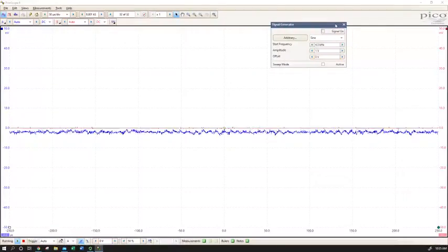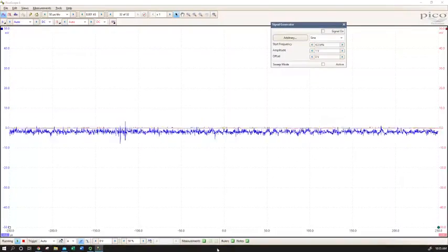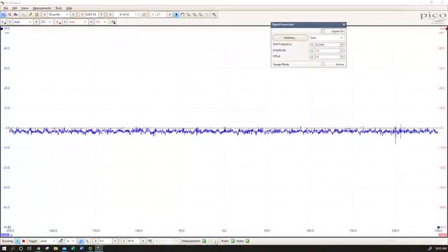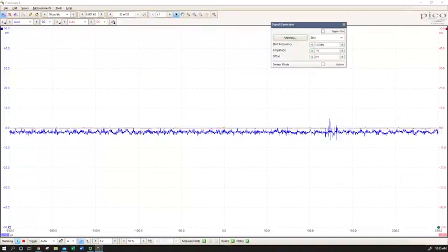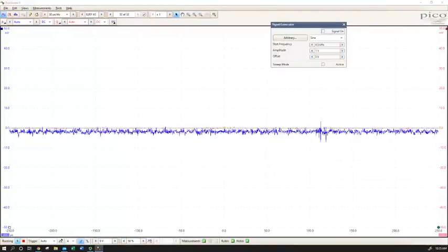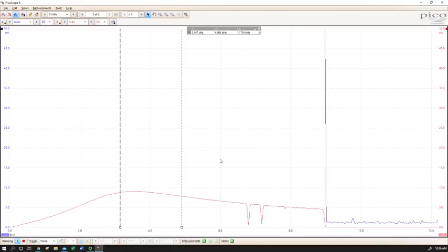I'm hooking up my circuit as we speak, so I'm going to double check. I'm collecting signal while I do that. That's why you're seeing noise. So I now have my primary from my 300 milliamp capability larger transformer in series with a 47 nanofarad capacitor, and in series with my indicator resistor. So back I go to my spectrum analyzer.